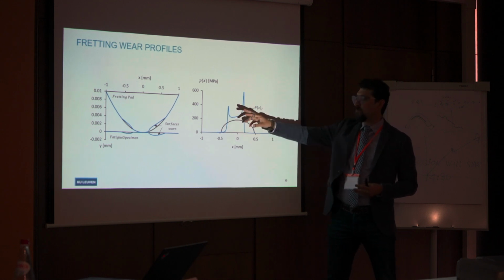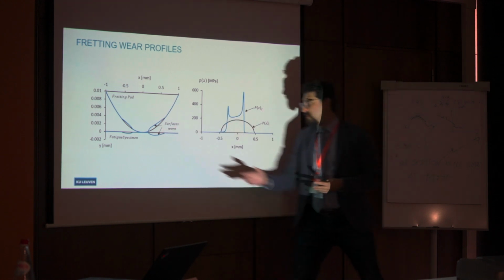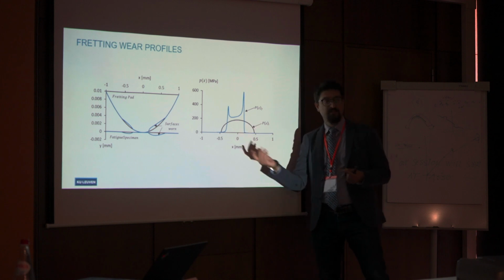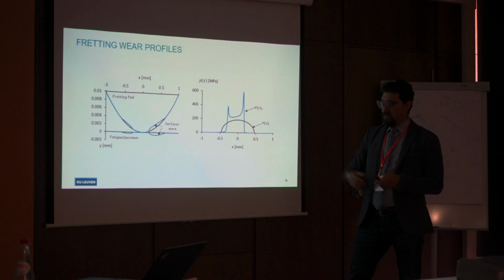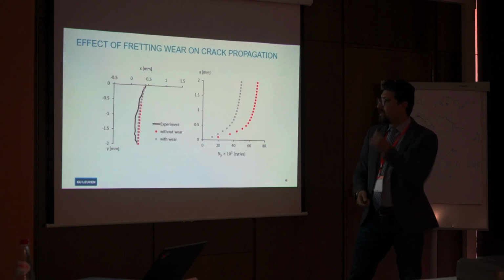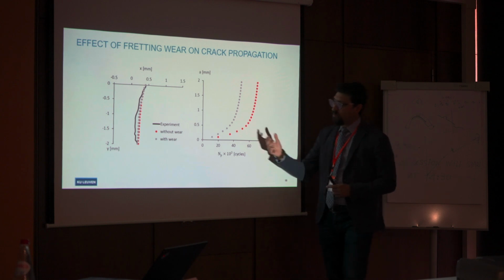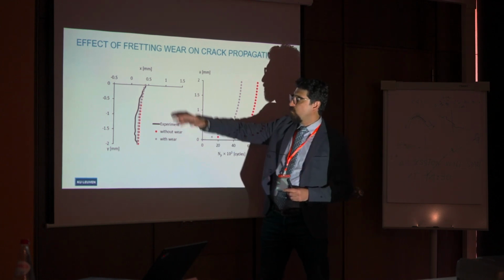This is the contact pressure distribution at the contact interface between the fretting pad and the fatigue specimen. That gives us the idea that the crack initiation lifetime and the stress distribution would be affected by this wear profile. Also, the crack propagation lifetime could be affected. So what we saw here is the simulation with wear and without wear.